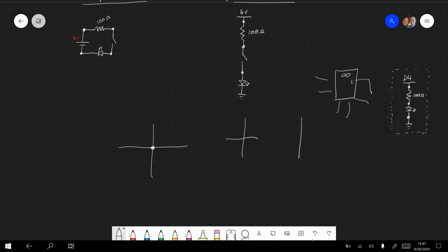Not necessarily in the same placement, like maybe I'm not putting my LED in the exact same row and column on the breadboard, but as long as I can get the actual connections and replicate the circuit itself, I should be good. And that's all that circuit diagrams are doing. They're telling us what is connected to what, not necessarily what is placed where.